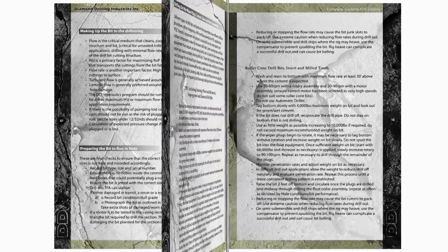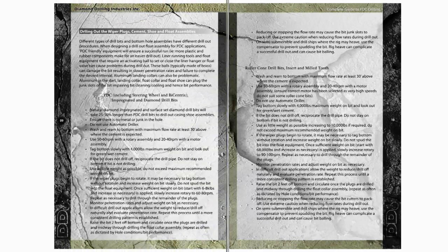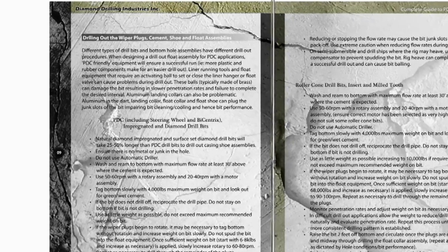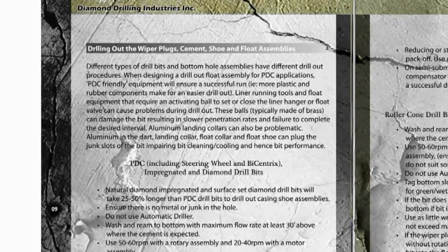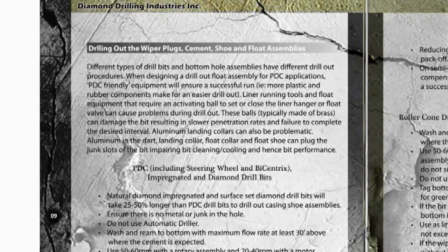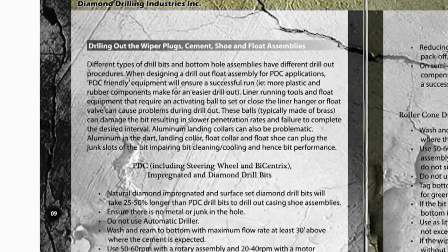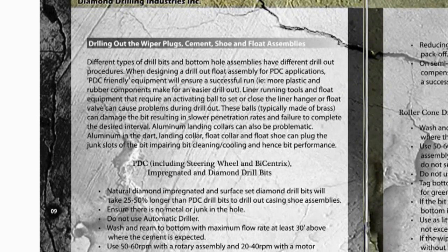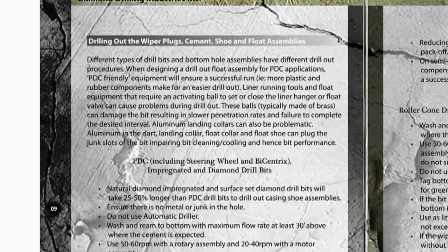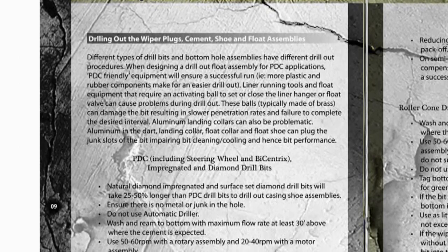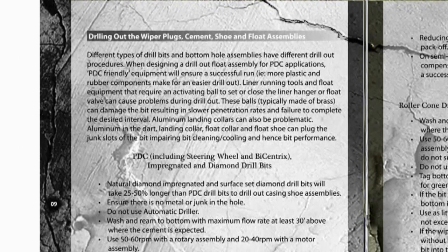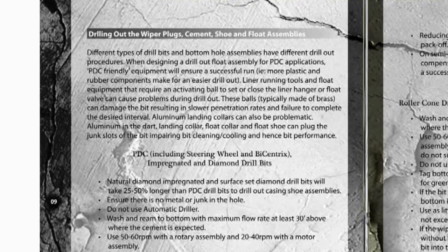Drilling out the wiper plugs, cement, shoe, and float assemblies. Different types of drill bits and bottom hole assemblies have different drill-out procedures. When designing a drill-out float assembly for PDC applications, PDC-friendly equipment will ensure a successful run, i.e. more plastic and rubber components make for an easier drill-out.